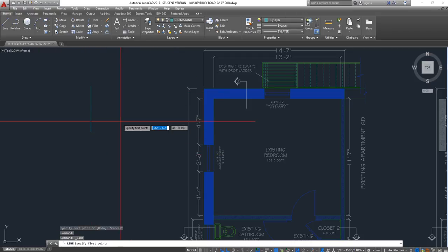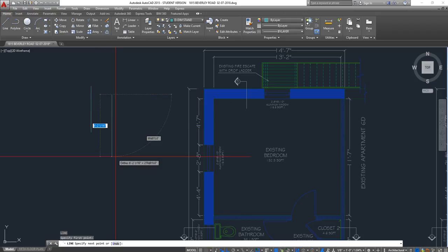And it's not doing it. Okay, let's see. L, enter. It is not doing it. Okay. L, enter, for some reason is not doing it. Okay, here we go. L, enter, and we said 4 feet, and in order for you to put the feet, it's on my keyboard, next to the enter. There is this button, and then I put 7, enter.